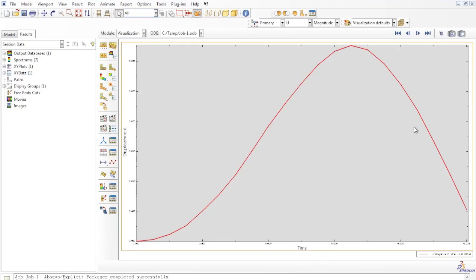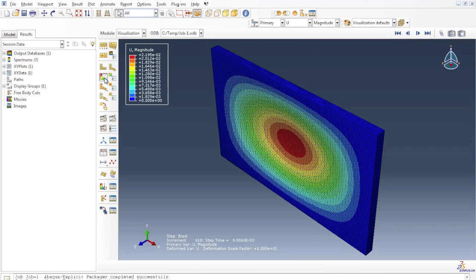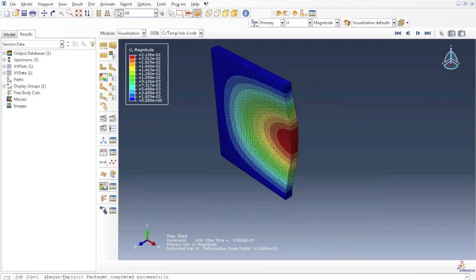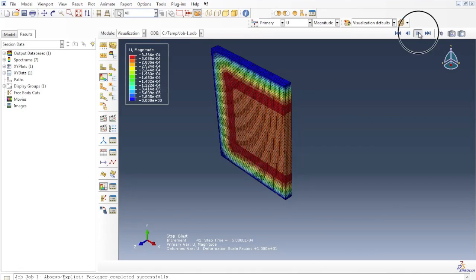The displacement then begins to fall, as the wall tends to return back to its original position. This is due to the wall being modelled as elastic. In reality, a displacement of 30 millimeters would result in the wall maybe cracking, but as it's elastic, that's what's happening. This is further emphasized by clicking on Activate Cut view. Click on that and then watch the wall displacing again.